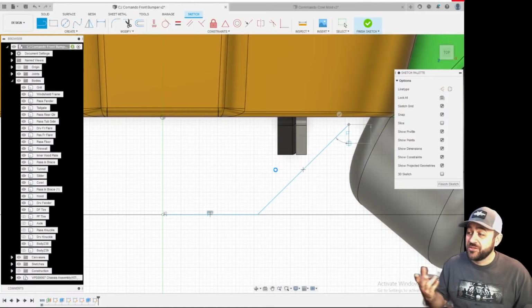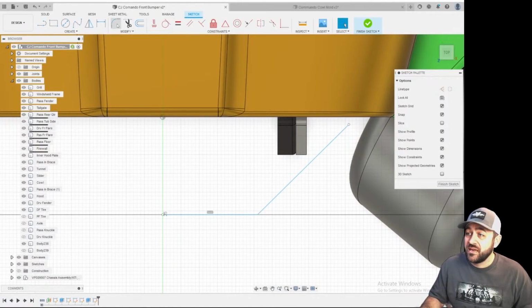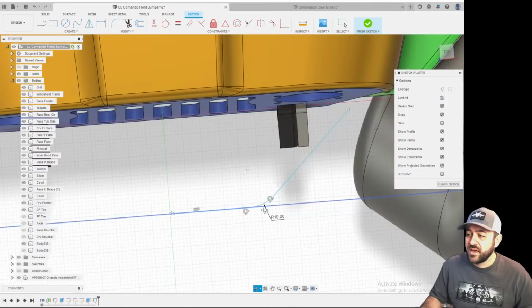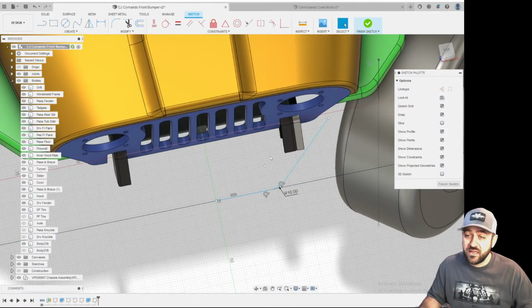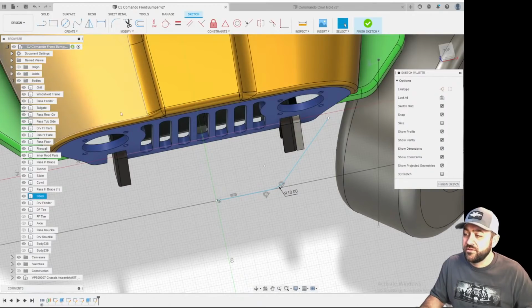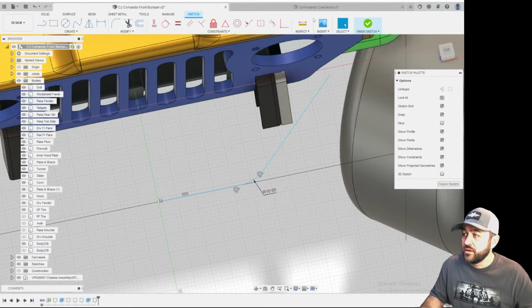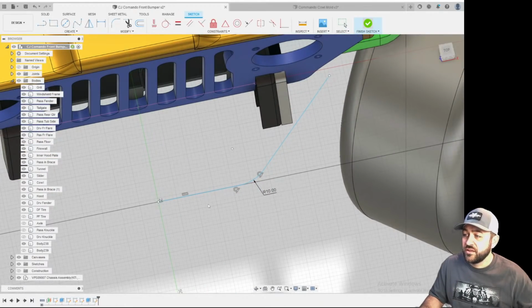So I'm just going to create a couple of tubes and then see how they look, and we can adjust from there. I'm going to throw a radius on this of about 10 millimeters, which is close to the bend radius of the center line of my tube for my solid rod tube bender. Actually, even for my regular tube bender for DOM. So I'm just going to hit finish on that sketch.